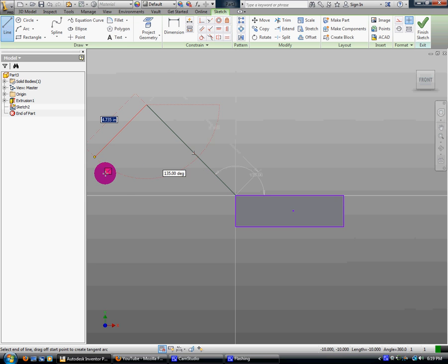And I'm going to draw this purposely off a little bit again because I wanted to show you. See how that forced it to go perfectly perpendicular? Remember, use your constraint tools, they're your friends. I want it to be perfectly perpendicular. This is my main line. I want this one to go perpendicular to it, and it's going to snap it nice and pretty. Perfect.